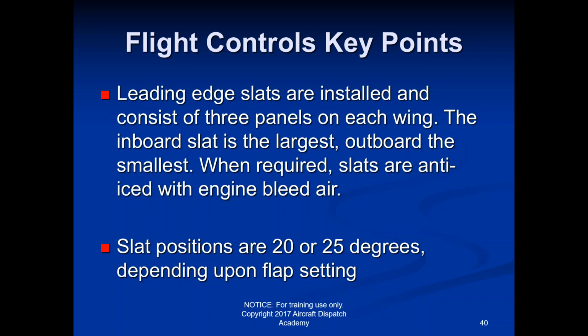When they put the flaps down, the slats are totally connected to the flaps. You can't independently put the slats down. When you put the flaps down, the slats are automatically tied to whatever flap setting you're doing. It's all connected to the same little lever. But it basically does the same thing and has the same effect as the flaps. It's just helping create more lift, but for this one it's going to be on the front side of the wing instead of the back.